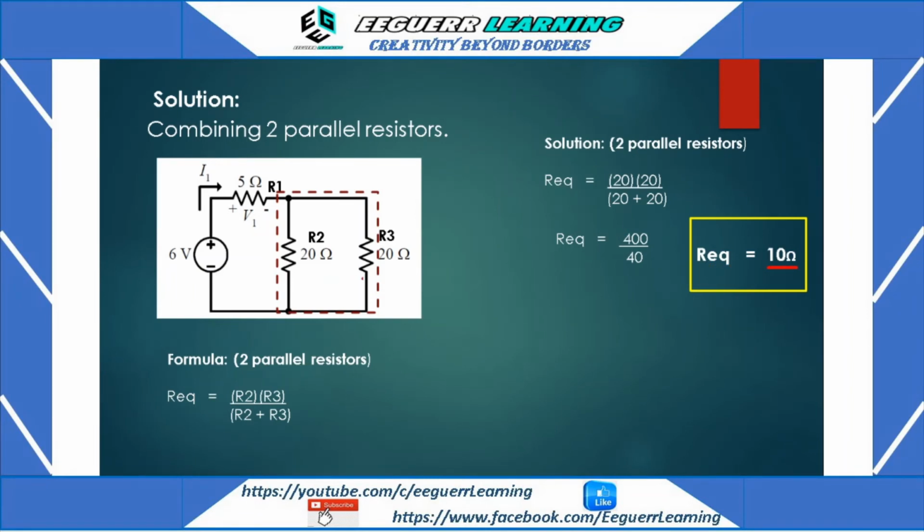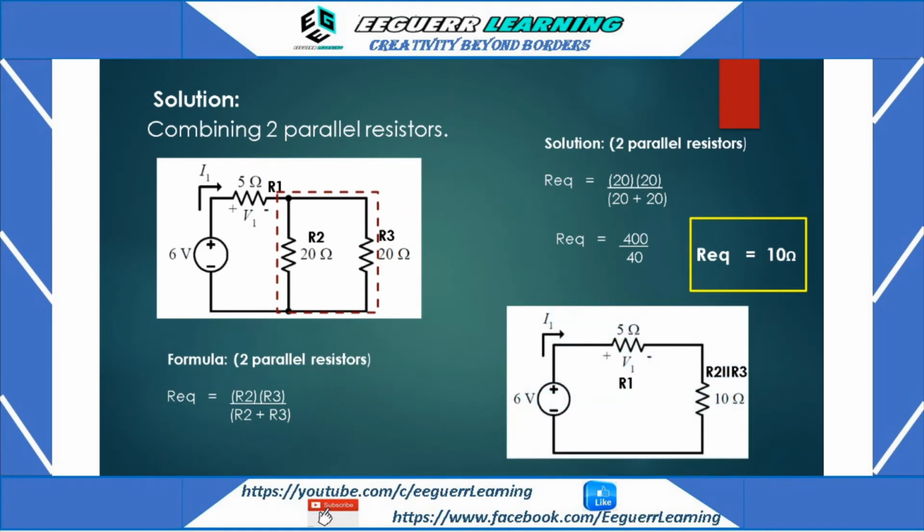Okay, so similar with the idea of the half of this resistor, one resistor. So again, if you have similar resistors in parallel, similar values, you just get the half of that. So the half of 20 is 10. Okay, to get your shortcut result. But if you want to do this, it will give us the same result. Okay, so let us continue for the equivalent circuit.